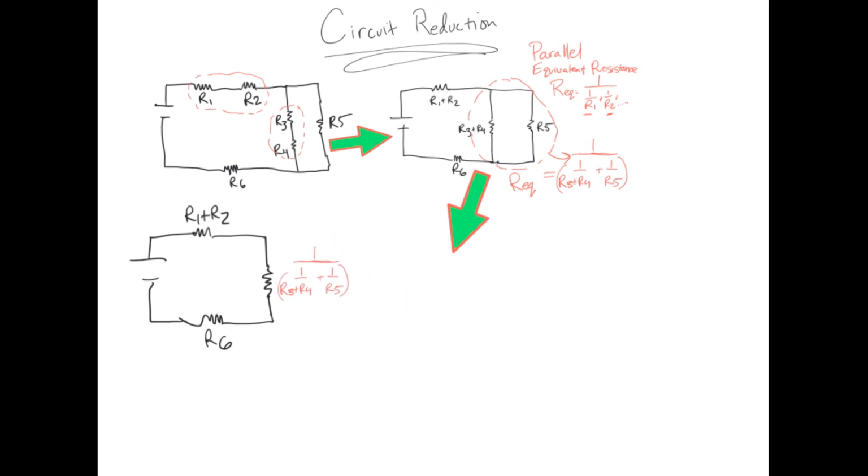That circuit here can be reduced one more time, and then really it's just acting like a single resistor if I just add up all 3 of these together, because now according to our series rules, you have 1, 2, 3 all in series, and you can just add them up.